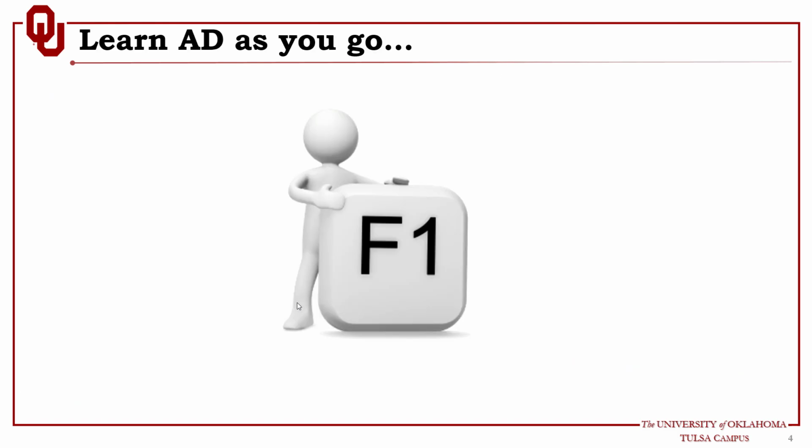And then again, I always remind you to learn Altium Designer as you go. Whenever you have a question or you are hovering over a command and you don't know how to use it, just move the cursor over that command, panel, or dialog and hit F1 on your keyboard, and Altium Designer will take you directly to the documentation where you can find comprehensive information about whatever was under the cursor.